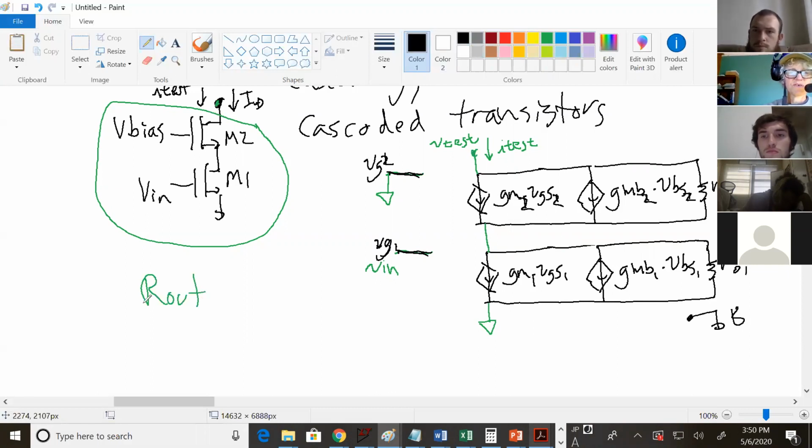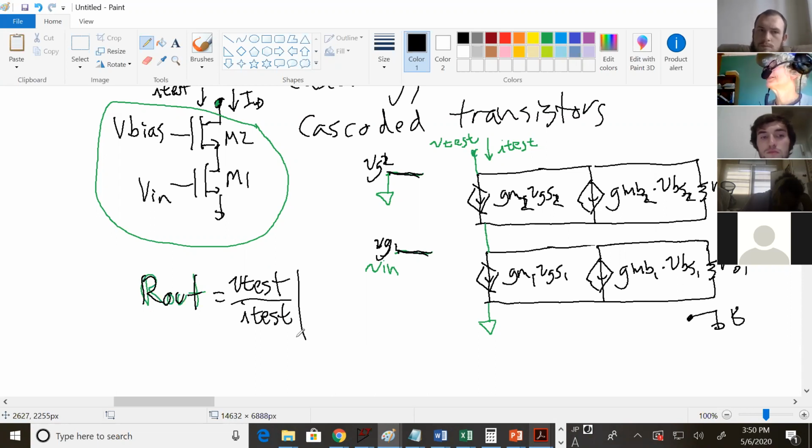So let's make that official here. We're looking for R out. And R out, you know, is V out over I out. Or sorry, V test over I test. Let's keep the names agreeing anyway. And then what nice thing do you get to do? Zero V_N. So let's do that.